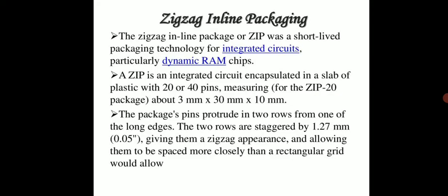And the next, zigzag inline packaging. The zigzag inline packaging or ZIP was a short-lived packaging technology for integrated circuits, particularly dynamic RAM chips. A ZIP is an integrated circuit encapsulated in a slab of plastic with 20 or 40 pins measuring about 3 mm by 30 mm by 10 mm.